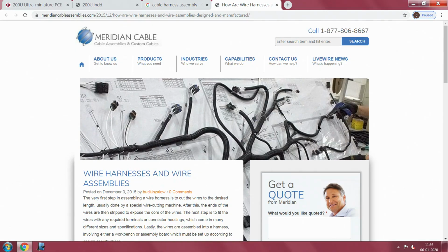So, I have a front panel, the rear, then you have the side panels, you have the top. Now, once you remove the cover, at least imaginatively, and you spread out all the panels on all the sides, it is again flat. So there you need to have this cable harness or cable form running along all the corners, and you need to spread it in all the directions and then get it ready. So, this is typically one of those flattened harnesses which has been spread out.